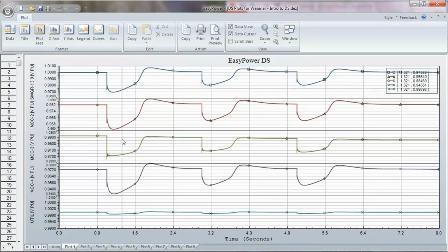So here are all the voltages. You can see for that motor sequence how low the voltages went. On the green one, which is where the motor started, we actually went down to roughly 87.9%. Look at the rounded characteristics. Kind of interesting. That's because other motors are supporting the voltage. Also, why is the voltage pulling up prior to the start being completed? This is due to the AVR control action of the generator. It's trying to boost itself.